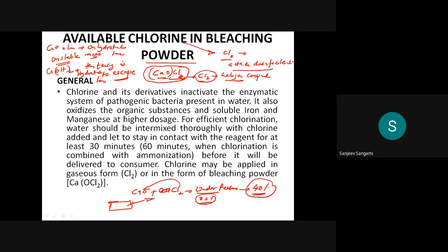Whatever the 40% or 20% you have, within 30 minutes all the chlorine gas is going to escape. That much it is unstable in nature. It is also very dangerous; if you are suddenly exposed to chlorine gas, you become unconscious. That's the main health significance.